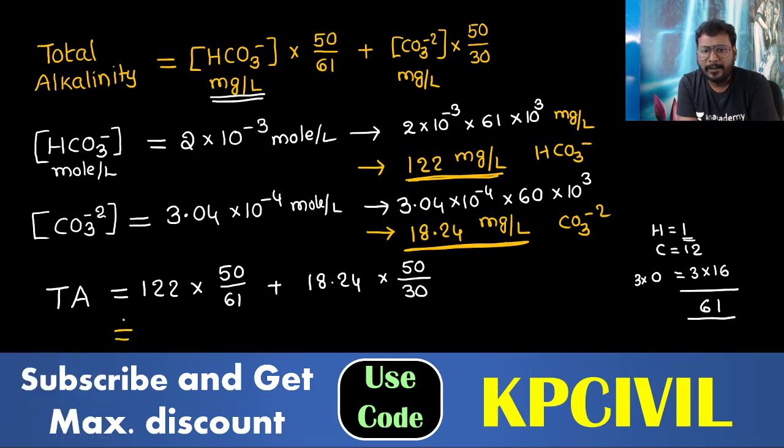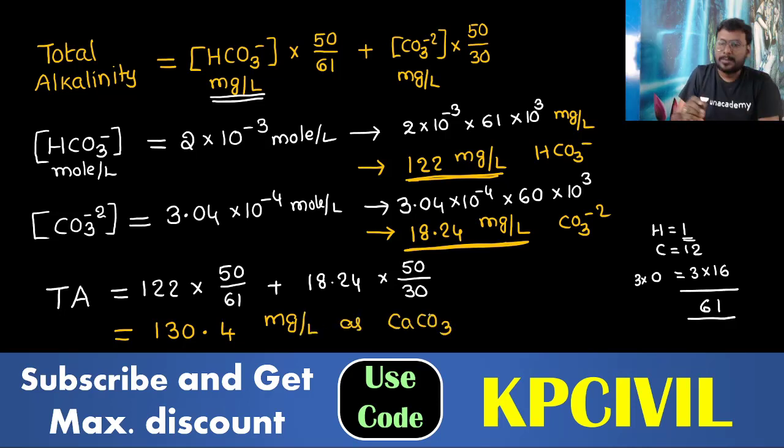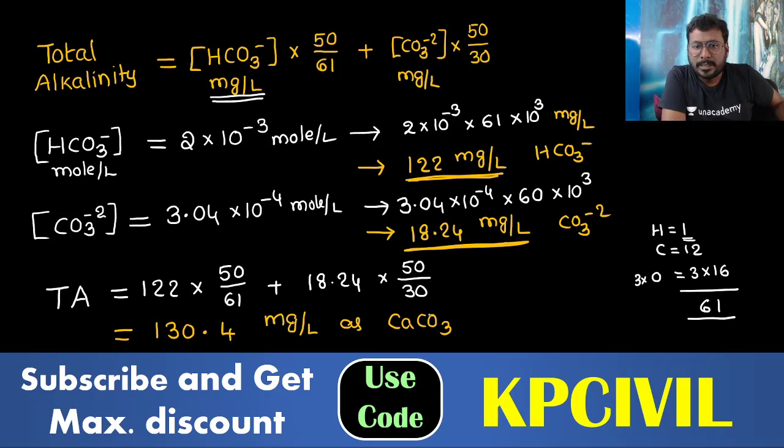Total alkalinity is 122 into 50 by 61 plus 18.24 into 50 by 30, that is, you get 130.4. What is the unit? The unit is milligram per liter as CaCO3.